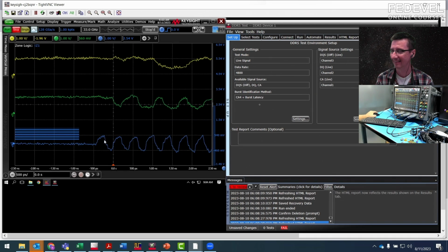Okay, there's a read because I could tell the signals are rise times faster, but the data doesn't start toggling until 1 or 2 bits after, because this is called the preamble. Okay, the preamble is like, let's charge up the line, and it's the whole setup and hold thing. We need to set up the strobe, the clock for the data, and have it ready so we can then reliably latch the data in.